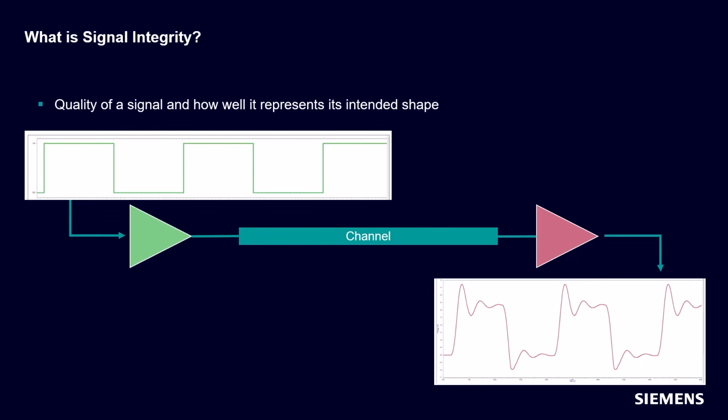At its core, signal integrity addresses how well a transmitted signal maintains its shape and characteristics as it travels from a transmitting device to a receiving device. The goal is for the receiver to correctly interpret the data, which means the signal must arrive with its amplitude and timing intact. Many factors can degrade a signal, but for this introductory lesson, we will focus on key aspects like amplitude distortion and timing variations.